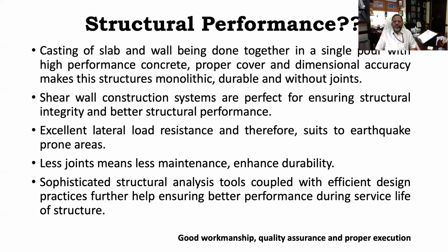Next comes structural performance. There is no doubt about it. Over the years, looking at how conventional construction performed during earthquakes, it has been found that shear wall construction is better, and this tunnel formwork system enables shear wall construction. And shear walls, as all of us know, are better as far as seismic resistance is concerned.